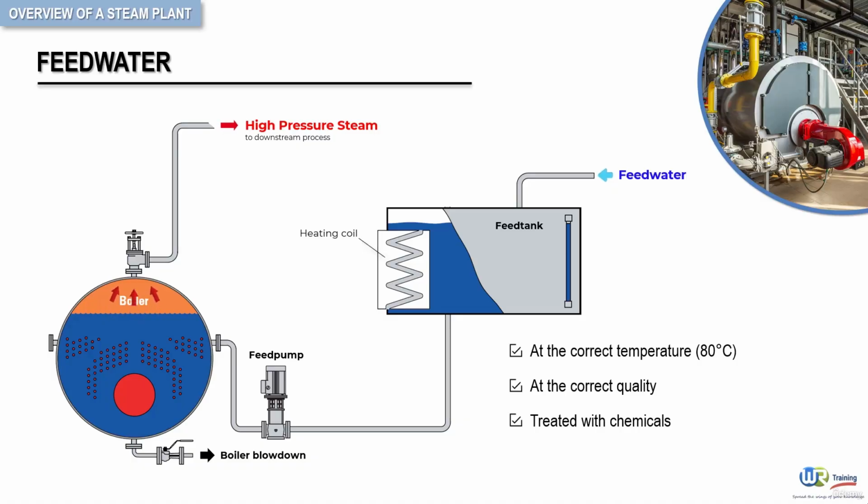It is important to note here that both feed water treatment and heating take place in the feed tank, which is usually situated high enough above the boiler. The feed pump, highlighted now on screen, will add water to the boiler when required. Heating the water in the feed tank also reduces the amount of dissolved oxygen in it. This is important as oxygenated water is corrosive.